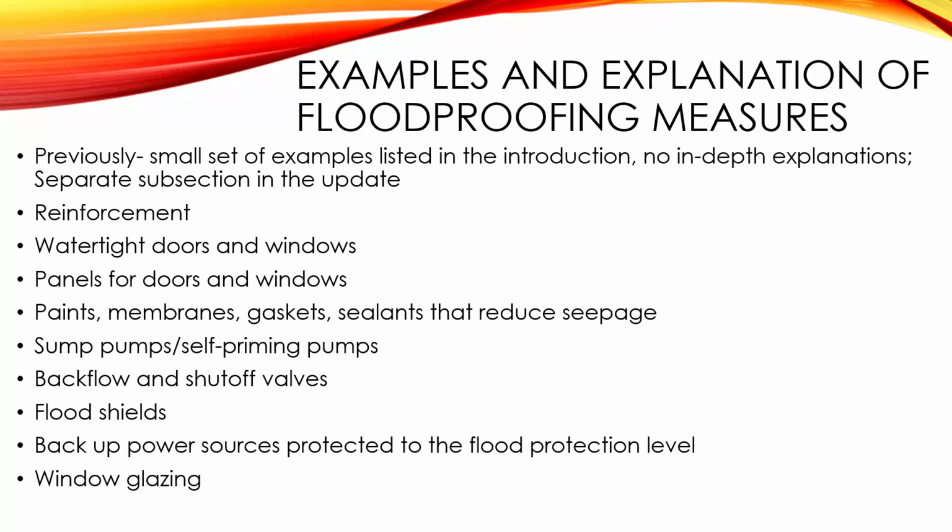Examples and explanation of these types of measures. So just commonly reinforcing the building, having watertight doors and windows, those flood shields that I mentioned, paints and membranes that conceal seepage or cracking. Sump pumps are a required part of the design.